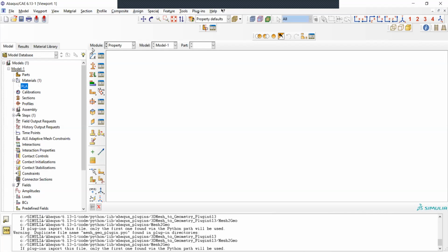So you see here, there's an additional menu on the top that I didn't talk too much about yet. In this, you have a drop-down menu. And if you just follow those steps, you can do everything needed to get your simulation ready and to run it. So first you have to have the part, then you generate the properties, which are the material properties and others. I will explain those. Then you assemble, if you have several parts, and you assemble the parts.